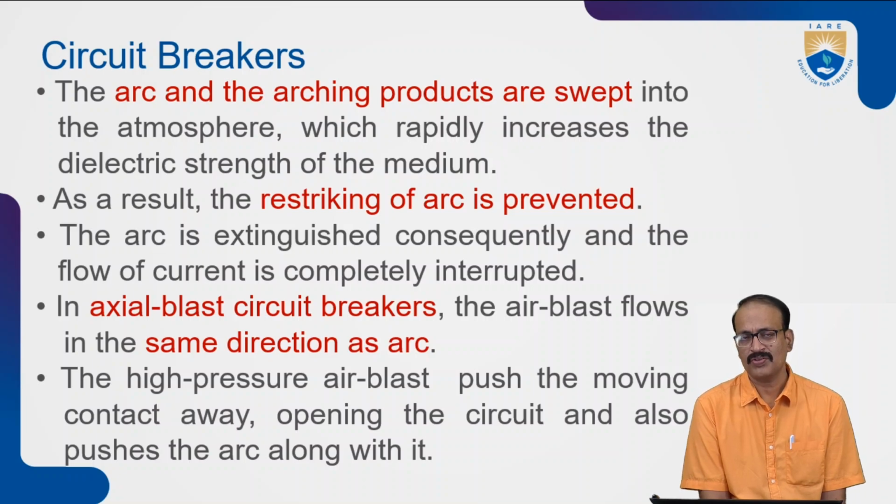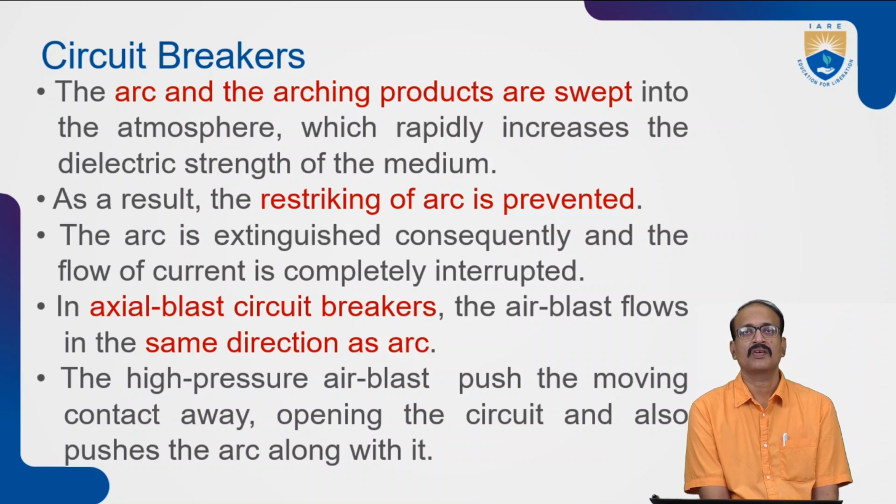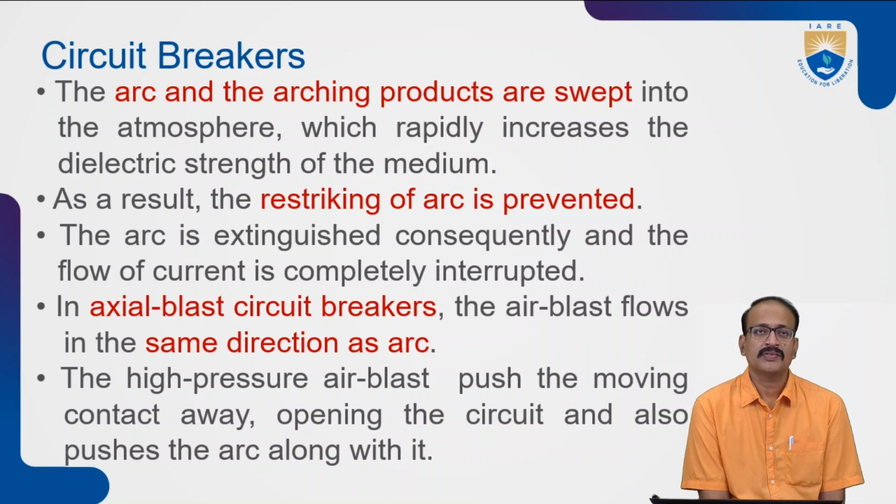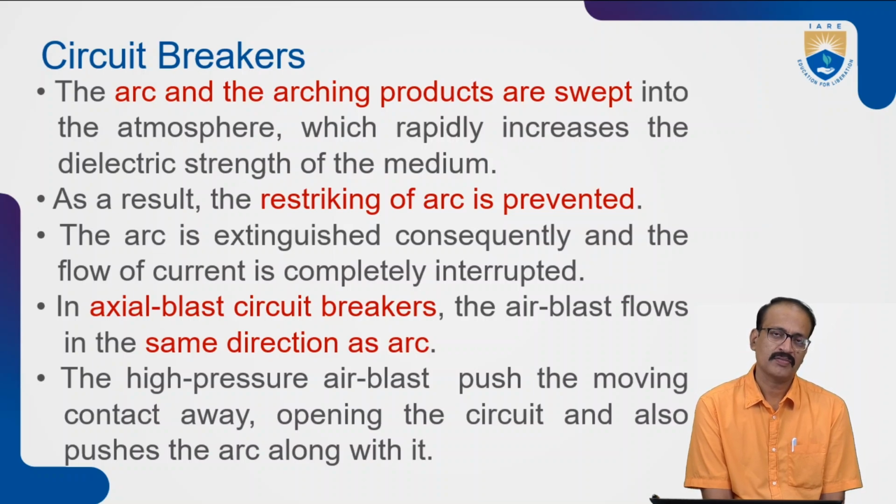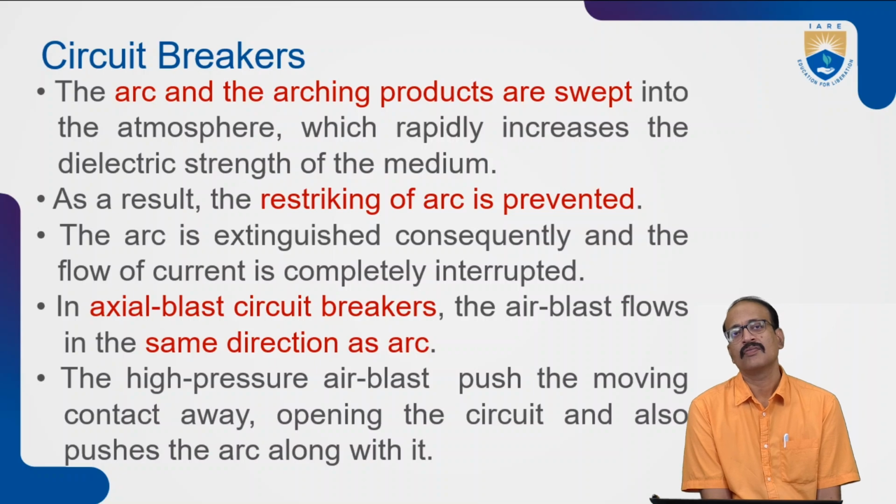Since there is no question of these particles staying there, there is no question of restriking occurring. As a result, the restriking arc is prevented. The arc is extinguished consequently, and the flow of current is completely interrupted. Once the arc is gone, the current will automatically stop.